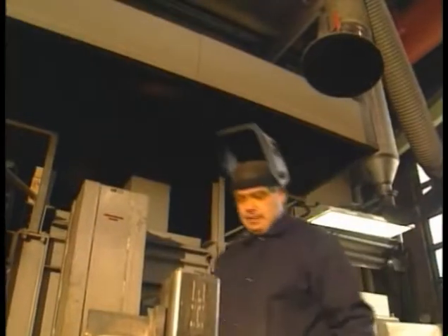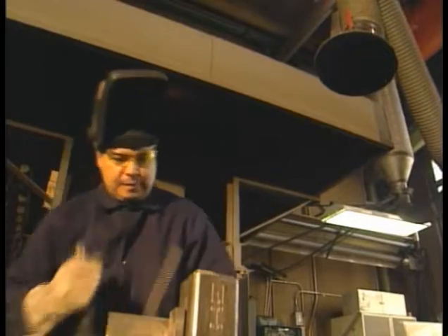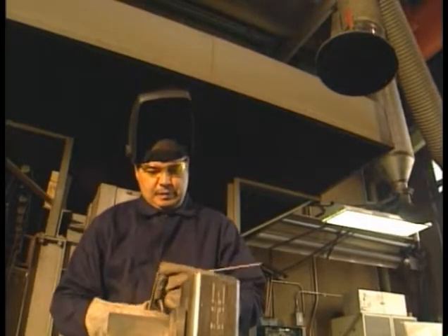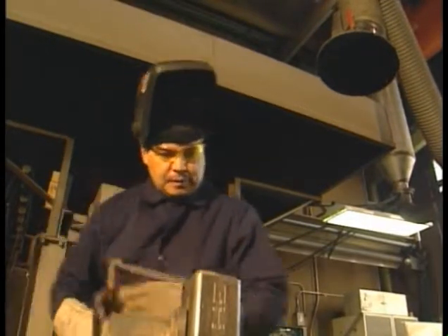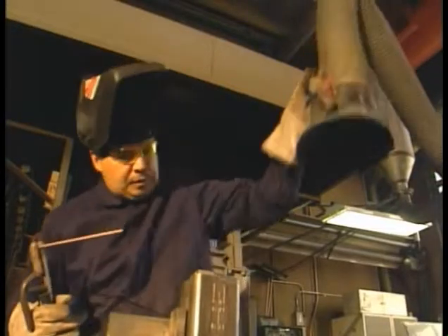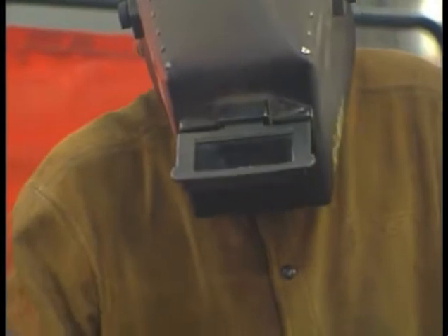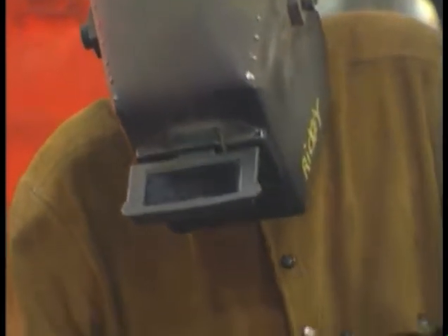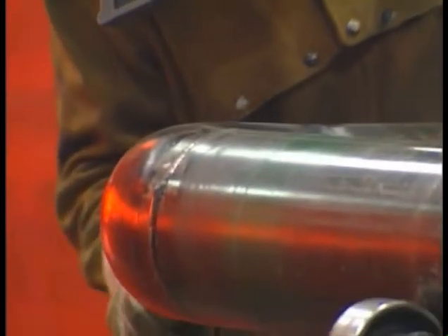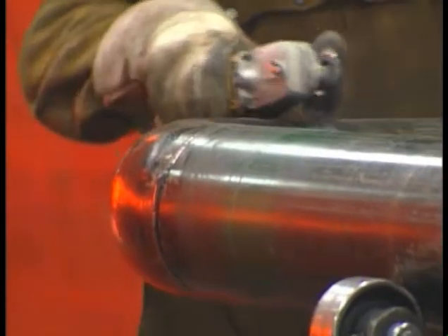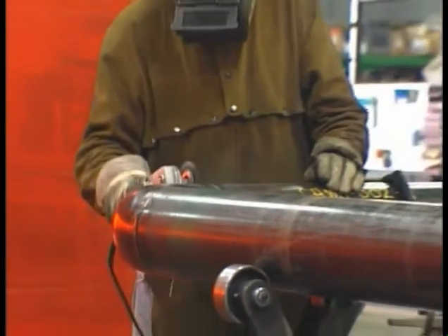The ultraviolet rays can also burn your skin, so wear long-sleeved overalls, shirts, and pants. Button up your shirt collar to keep your neck and throat from getting a burn. Leather aprons, jackets, and pants specially designed for welding are the best protection from burns. Keep all of the clothes you use for hot work clean and free from oil or grease so they don't ignite and burn.